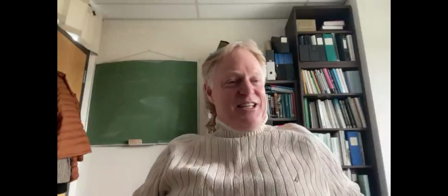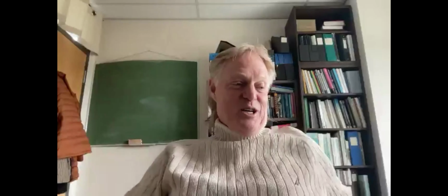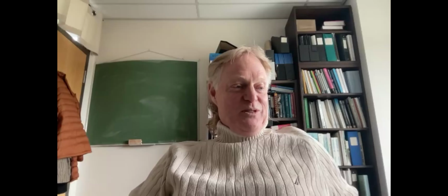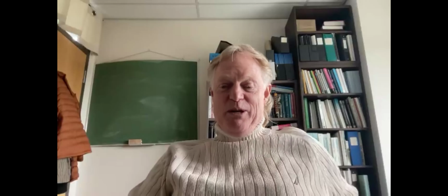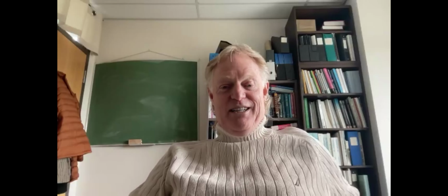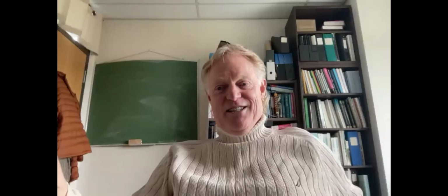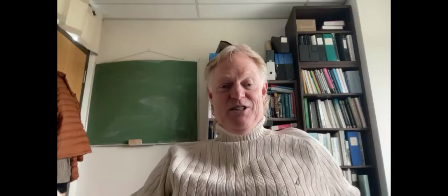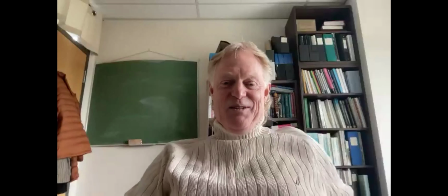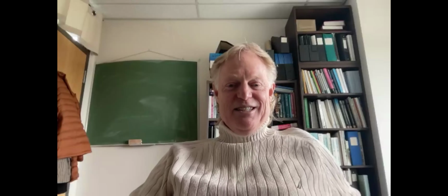There isn't a single common mistake. There's all kinds of very innocent errors. I was teaching a course a couple of years ago, and I'm not going to out the individual, but one person taking the course had been working in BPS for 20-some years, and his simulation results looked really odd. And he made an extremely innocent mistake when he typed in the thickness of an insulation. Instead of putting 10 centimeters, he put 100 centimeters. That's a simple data entry problem. And we all do it. Those are common mistakes of just not doing enough scrutiny and checking of our inputs.